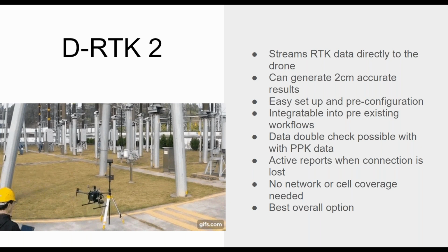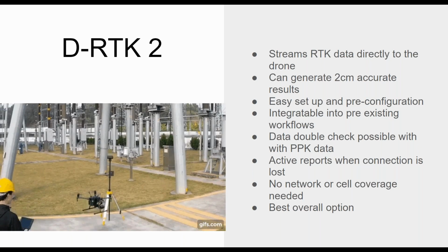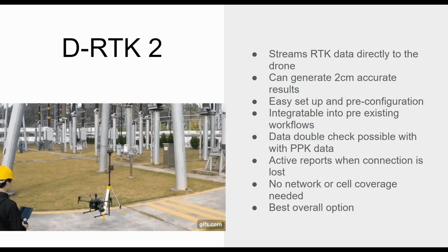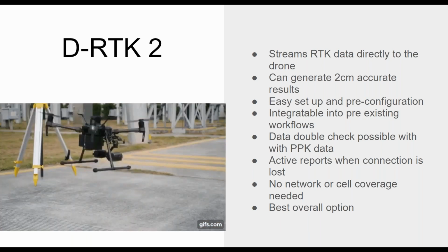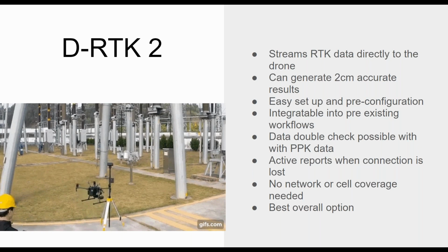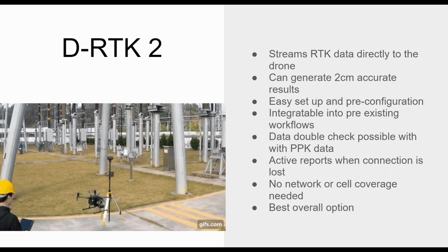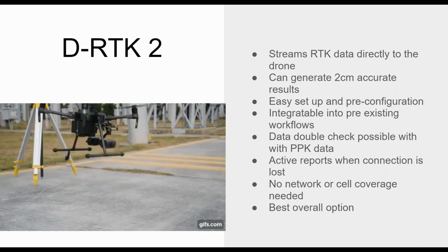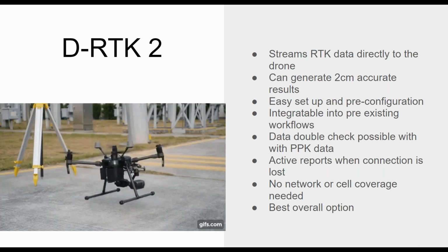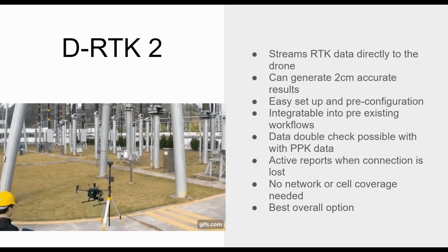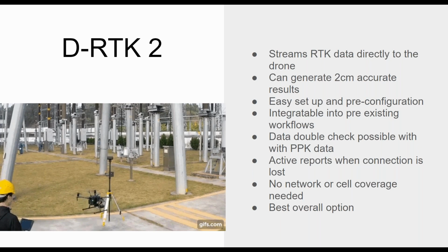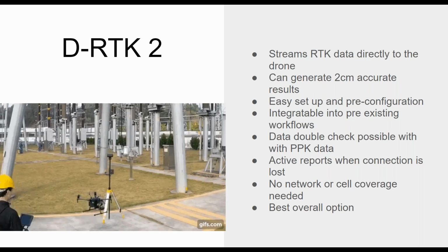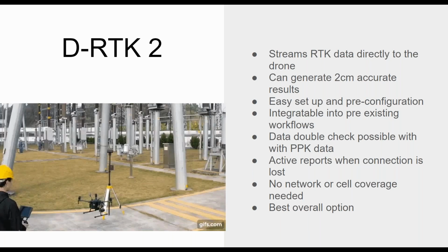And what it does is it lets you troubleshoot on site, rather than finding this error or this RTK drop in post and having to come back and try to fly the same site once again. And because you are using a live stream RTK data, just like with your third-party base station in the NTRIP, you can use traditional PPK methods to back up and check your work, making this method incredibly reliable, incredibly accurate, and incredibly easy to use.